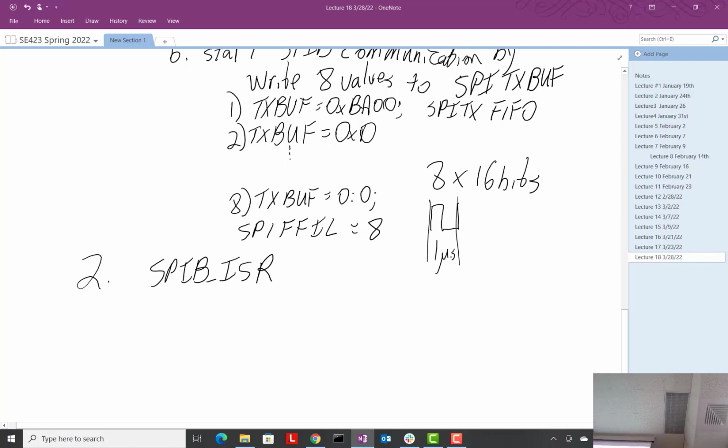So what do we got? 16 times 8, 16 times 4 is 64, so 128, is that right? 8 times 16, am I right on that? 32, 32, 32, 32, right. So 128 microseconds later, approximately, it'd be a little bit longer than that because of the time till the interrupt occurs and all that, but approximately 128 microseconds later, that's when this happens. Because when we send 8 things, we receive 8 things, don't we?